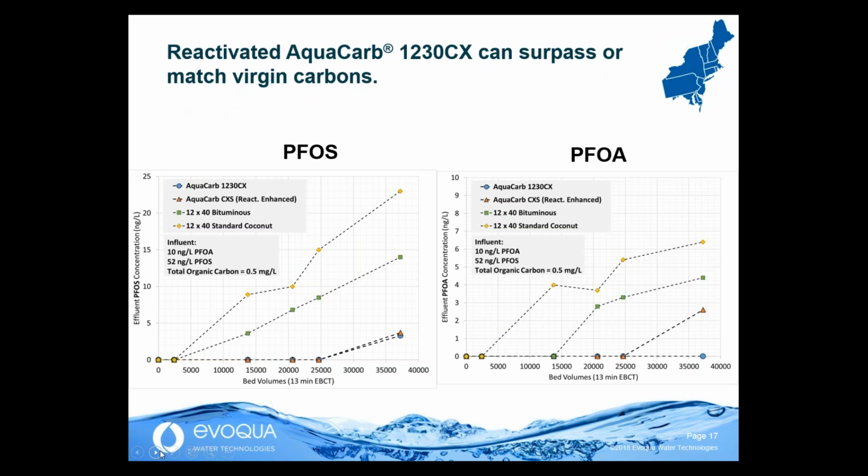One question that we get asked very frequently is, can I reactivate? As Caitlin mentioned earlier, with the reactivation process, we're able to destroy these compounds. So reactivation is a viable option. The second question is, if I can reactivate, what's it going to change in terms of performance? What's shown here with the PFOS and PFOA is that we have nearly identical performance for a reactivated enhanced carbon versus its virgin parent. This is very important economically and also in terms of being able to reuse the material.